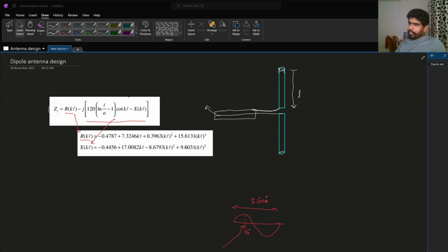If you have any requirements, like if your Wi-Fi range is less and you need to put your antenna a little bit far away from your Wi-Fi, then you can purchase some coaxial cable and make a dipole antenna yourself and put it on the Wi-Fi modem so that the reception will be increased. And the second application, a day-to-day life application, is if your laptop has less range, you can open your laptop and connect this antenna externally, so you can increase the range.